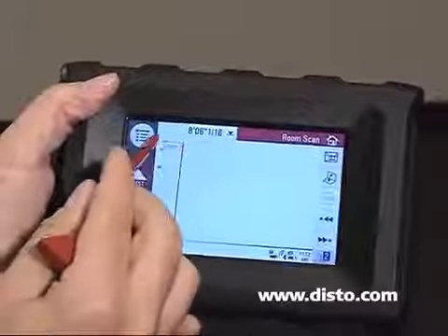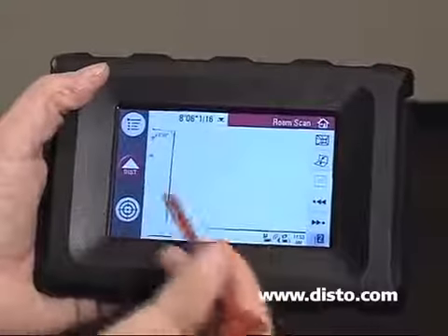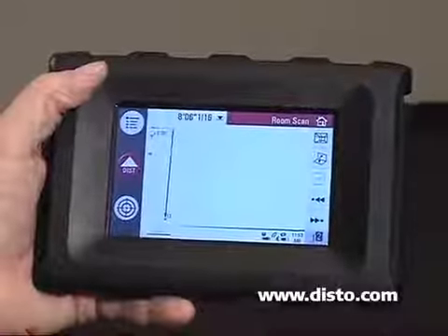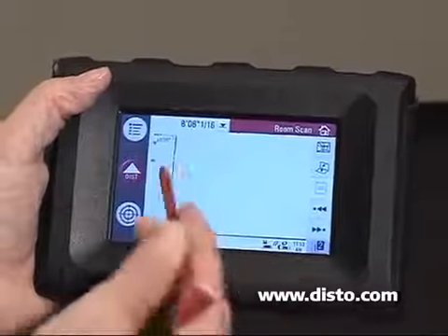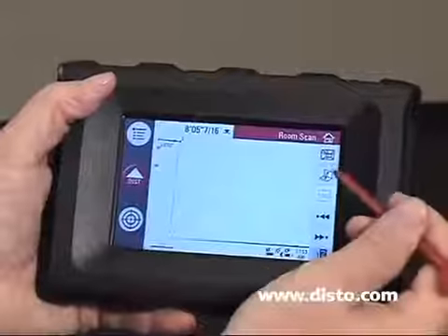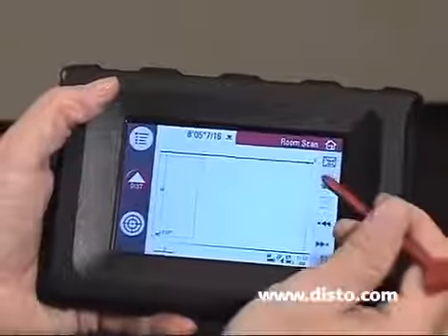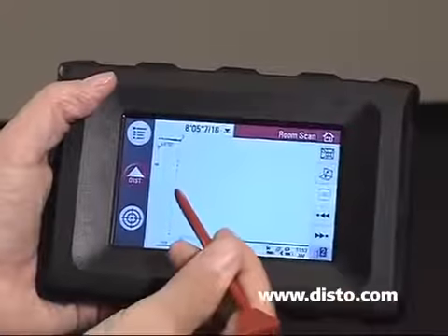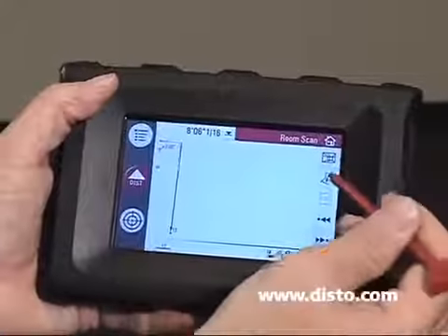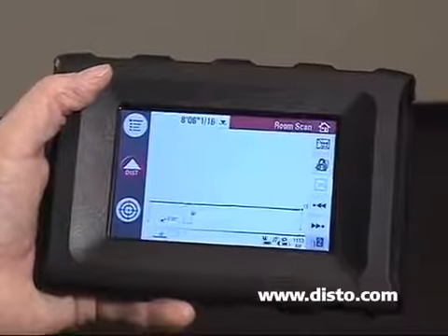You can see that there's the first section that we had done earlier. Here's our second wall plane. Now it's pretty small because right now it's scaled so that everything fits into the view screen. I can select on that first wall segment that we had done at an earlier time, unfold on that, see the door located in that segment, fold it back up again, hit our new line segment and our new wall plane, unfold on that segment, and see the new door located in that segment.